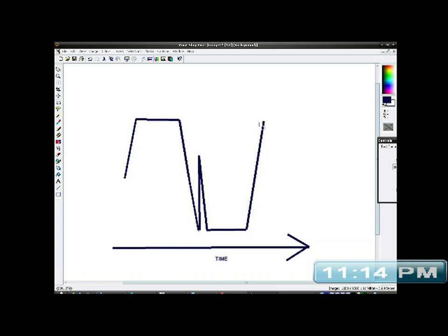There's another pulse, obviously, on the other waveform, but we're just going to focus on one half the waveform right now, because by using a longer lead in series with a capacitor, right, imagine this lead is 10 feet long or something, then to connect to the capacitor, that would automatically create a delay anyway because of the inductance of the wire.